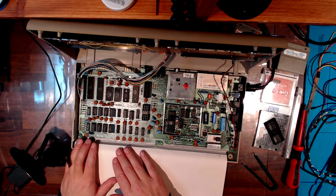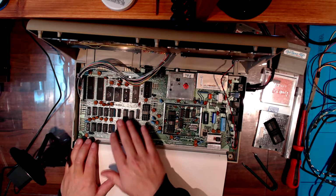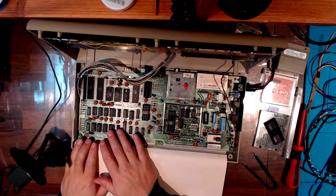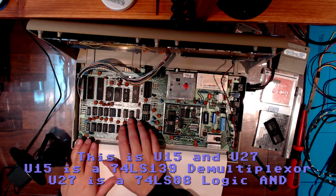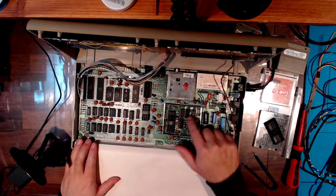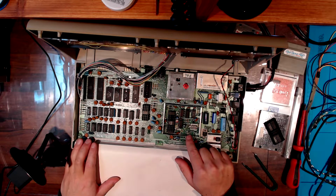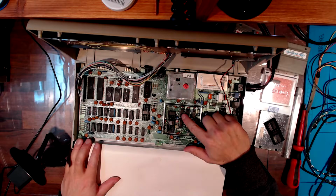And that's what I kept doing. I tried swapping all of these chips. I swapped the ROMs, I swapped the PLA, I swapped the RAM, I swapped these two, which I don't really know what they do at the moment, but they're some kind of logic chips. Those 4 chips were the last I tried to swap out. And what it ended up being was this chip right here.